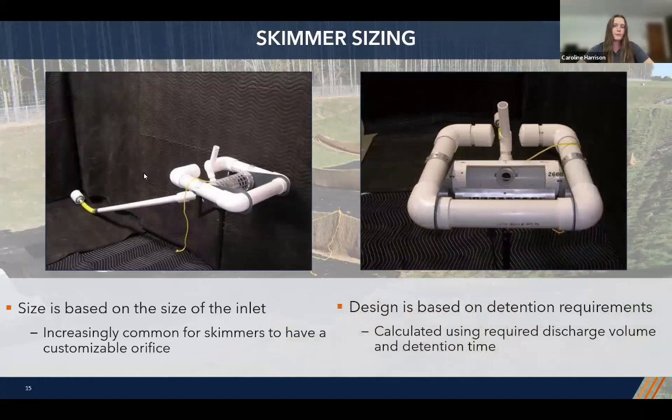The size of the skimmer is based on the size of its inlet. It's also increasingly common for manufacturers to provide customizable orifices or inlets to allow for even greater control over these discharge rates. When we're designing a sediment basin and a dewatering mechanism on a construction site, the skimmer design is based on the sediment basin detention requirements. The required skimmer size will be calculated using the required discharge volume from the sediment basin as well as the detention time.